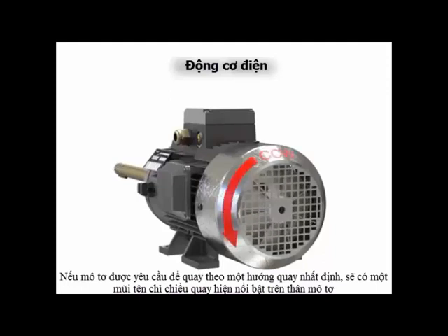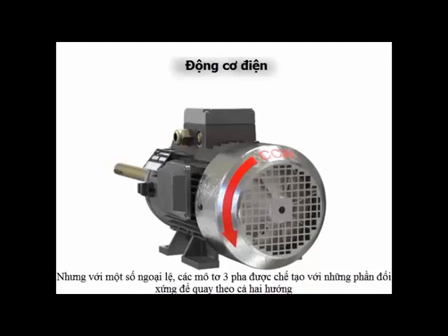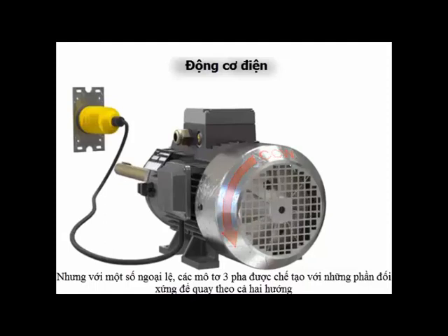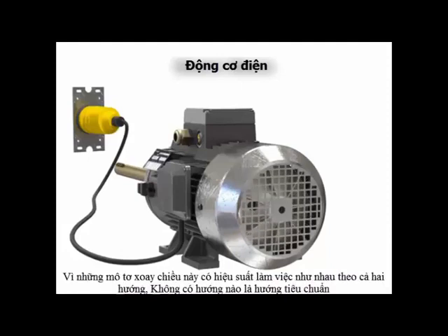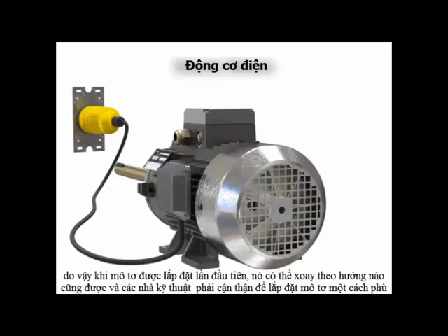the frame. But with few exceptions, most three-phase motors are made with symmetrical parts so the motor can rotate in either direction. Since these multi-directional motors are equally efficient in either direction, there's no standard direction of rotation. Therefore, when a three-phase motor is first connected, it may run in either direction, and technicians must be careful to